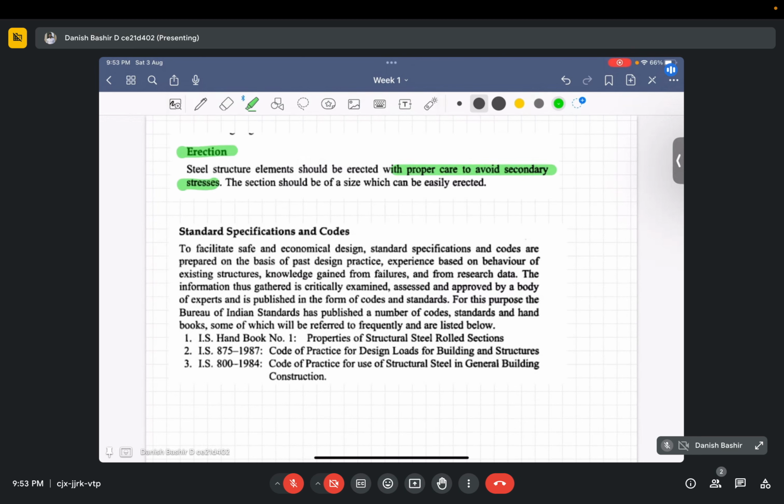For example, when some huge I section or C section is being erected for a column, it should be properly handled and erected in a manner so that it does not induce any secondary stresses into it, because it will create a lot of problems during its service life. It will create issues for that structure. The section should be of a size which can be easily erected. That is also important.